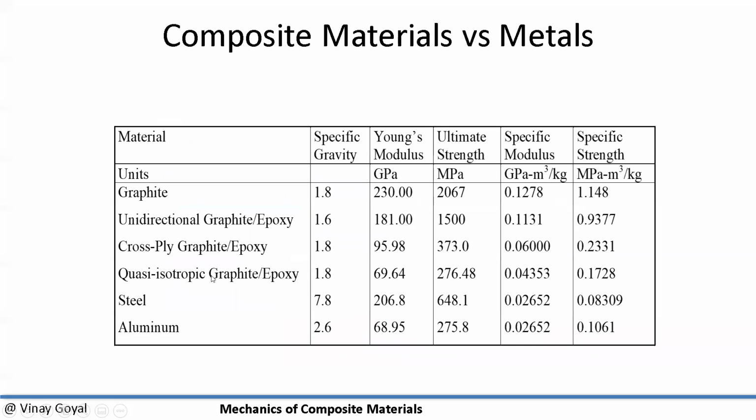And we covered this picture already once. The point I want to make in this picture is very specific to one thing I want to point out, because I covered this already in a lot of different flavors. But the main point I want to make is if you select a composite structure and use a standard quasi-isotropic material, which is 0 plus minus 45 90 symmetric. So 0 plus minus 45 90 symmetric is your quasi-iso.